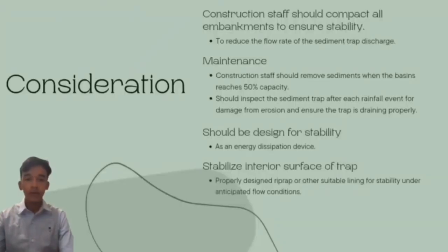Thank you. My name is Muhammad Luqman Al-Hakim bin Zulkifli. So I will continue with the considerations. First, for the construction, staff should compact all embankments to ensure stability and to reduce the flow rate of the sediment trap discharge. Second, maintenance. Construction staff should remove sediments when the basin reaches 50% capacity and should inspect the sediment trap after each rainfall event for damage from erosion and ensure the trap is draining properly.